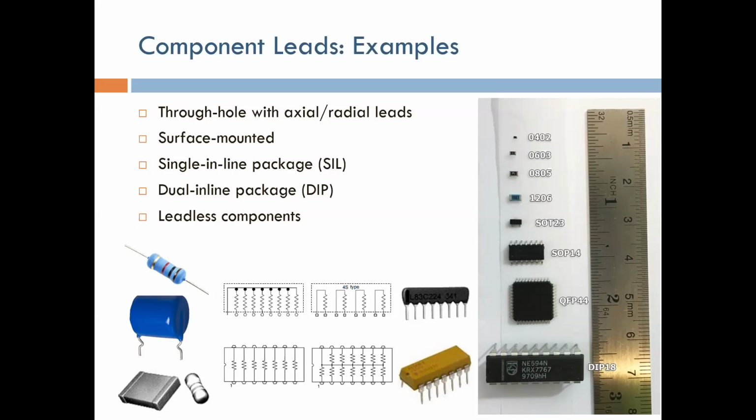If the resistance is used in a circuit board that is not intended for power, but for signal, then you don't expect to have any problem with power. You don't need a large component in order to dissipate the heat. So you can use very small packages like the 0402 in order to have a very small circuit board. You can have thousands of resistors in a very small area like a centimeter by centimeter. See here, this is just an inch. You can put maybe 500 of these in a 1 inch by 1 inch board.